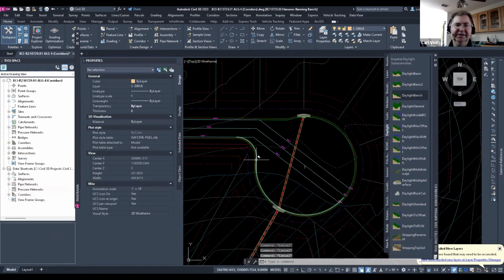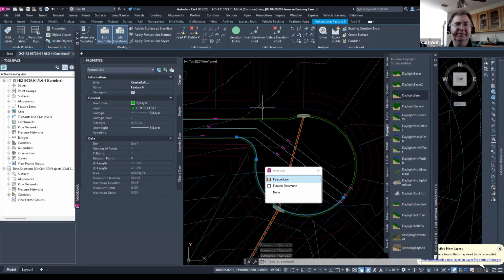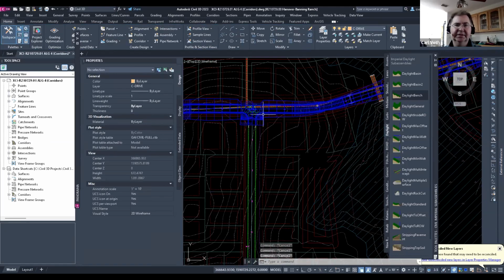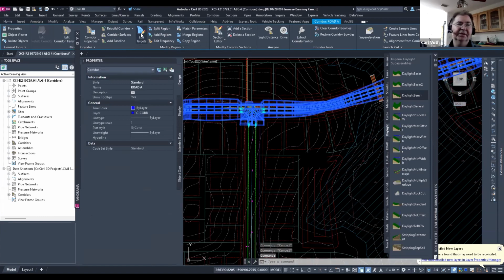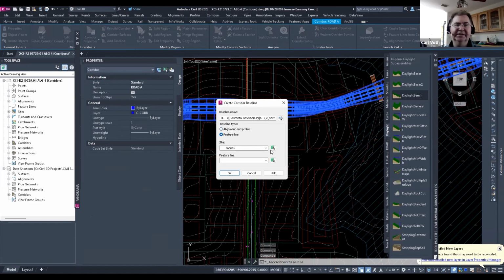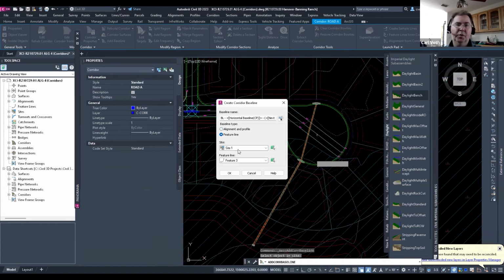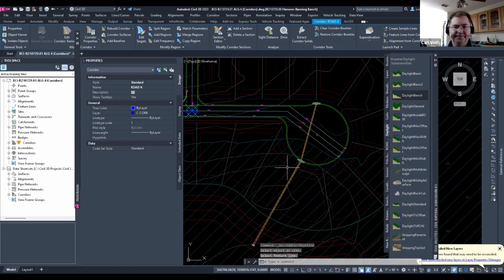All right, so cul-de-sacs seems to be another question that keeps coming up in my land. You come through, and I'm going to completely go down to a whole separate area here. And I'm going to use a feature line for my main point here. Now, when you do this feature line here, when you select the site, it brings up all the feature lines that you have on your site. The top one may not be the one that you necessarily selected for your site, so double check. In this case, it's going to be feature 6 for us.